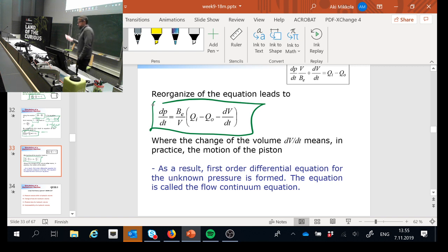Okay, now look at what I have in my equation here. I have here P dot, and I have one more in-class quiz. I'm asking what is the thing that I'm ignoring in the method. Remember the lumped fluid theory, we are not accounting for the pressure waves. But other stuff that I have here, the effective bulk modulus, which is associated with flexibility, is accounted for in the equation.